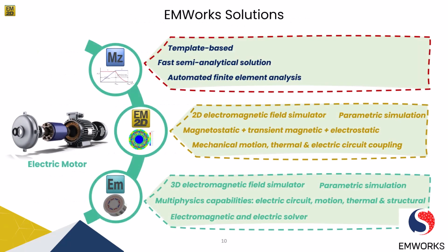So, to analyze and to evaluate the motors, we have different solutions. First, we have the Motor Wizard tool. It is a template based motor design software that allows the user to accurately solve both electric and magnetic problems. It includes electrostatic, magnetostatic, and transient solvers equipped with integrated analytical and finite element based solvers.